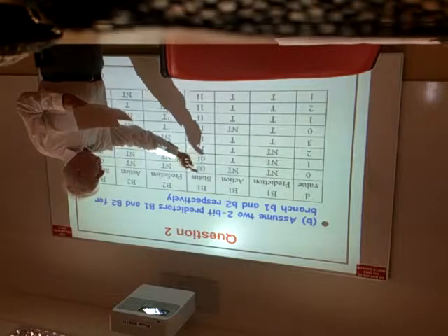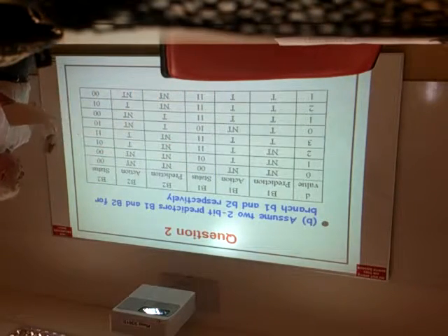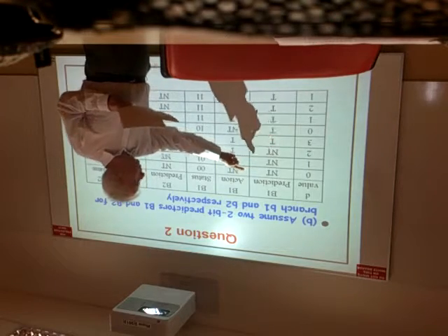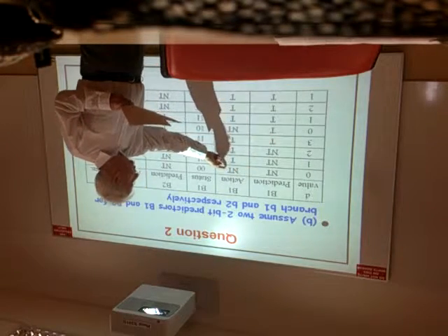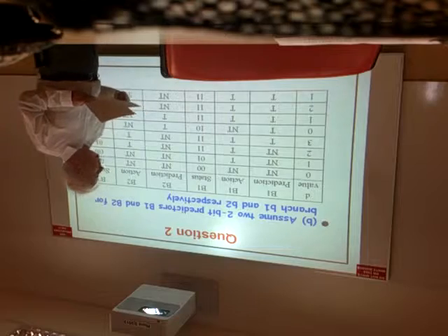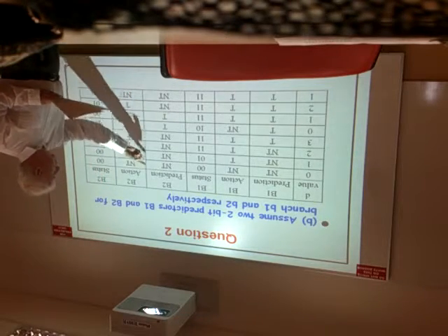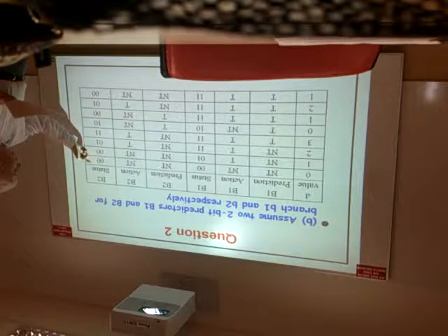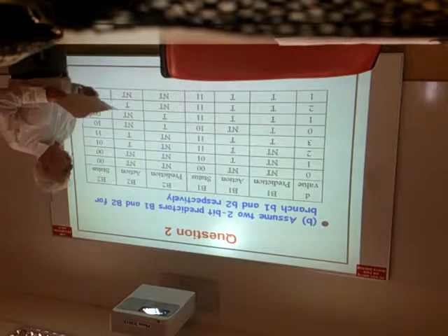We start off with the status of 0, 0 for both b1 and b2. So b1 predicts not taken, and it's correct, it's not taken, so the status remains 0, 0. And similarly for b2, it predicts not taken, the action is not taken, and stays 0, 0.